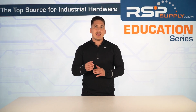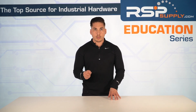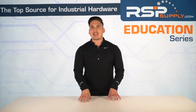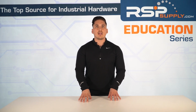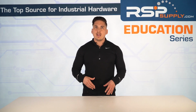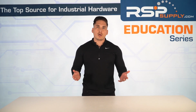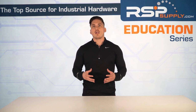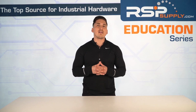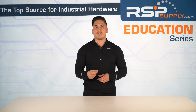So let's recap. In industrial automation, timing is everything, and that's where the difference between deterministic and non-deterministic communication becomes critical. Deterministic protocols like EtherCAT, Profinet IRT, and SERCOS deliver data at precise, predictable intervals. It makes them ideal for real-time control within motion systems and safety-critical operations. Non-deterministic protocols, on the other hand, offer a lot more flexibility and scalability, which makes them great for tasks like cloud logging, monitoring, and non-time-sensitive data exchange.